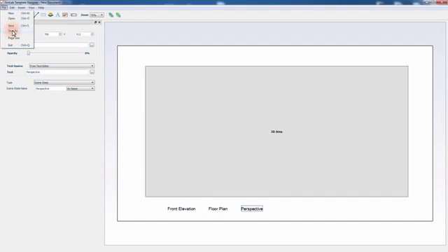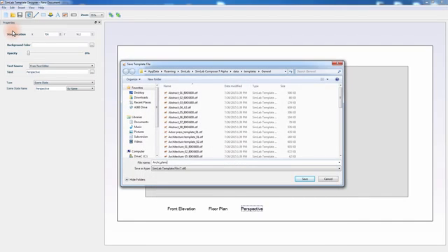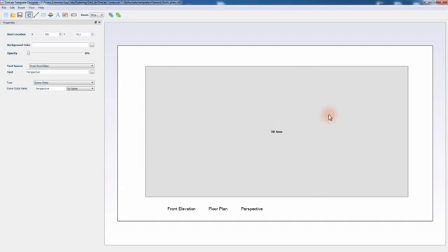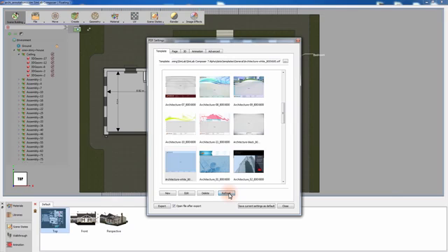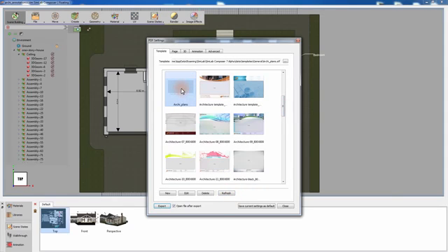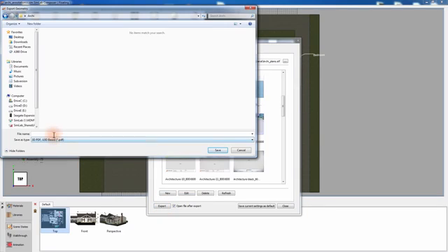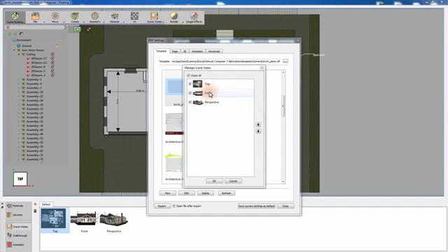Save the created template and close the template editor. Then click Refresh and select the template you created and click Export. Set the location and the file name for the PDF you are about to create and click Save. Make sure that you have all the scene states that you need checked and click OK.